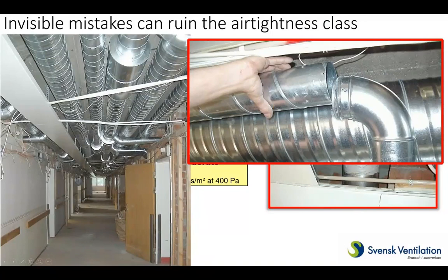But on the male part here, we have two holes. And the reason for this is that the installer has put the two parts together. He has found that this elbow didn't point the right way. He must adjust the angle.